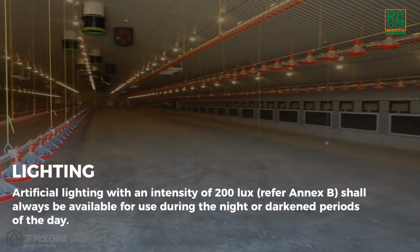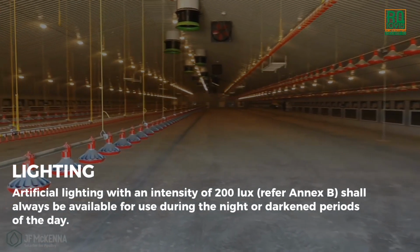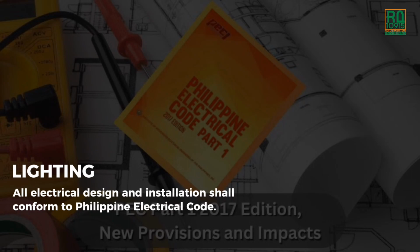Lighting. Artificial lighting with an intensity of 200 lux, refer Annex B, shall always be available for use during the night or darkened periods of the day. All electrical design and installation shall conform to Philippine Electrical Code.